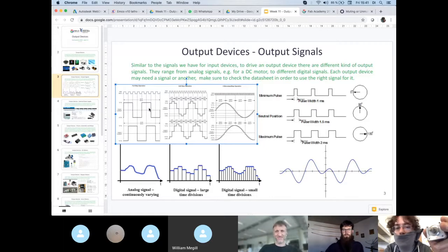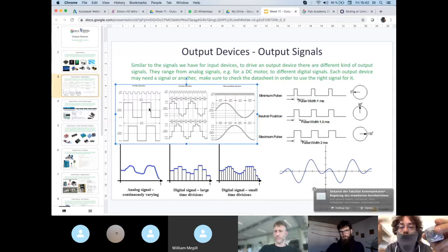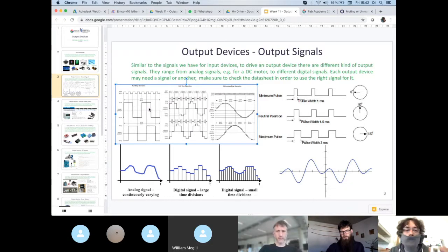So you have not 200 steps per rotation anymore, but 200 times 256, for example. To make it simple, with half-step rotation, each step becomes 2 steps, so from 200 steps per rotation you have 400 steps per rotation.